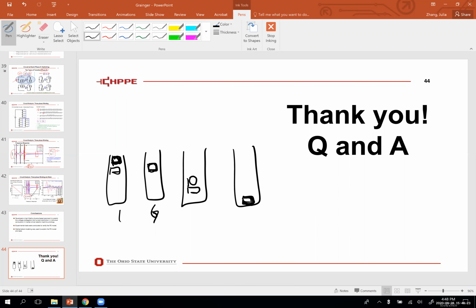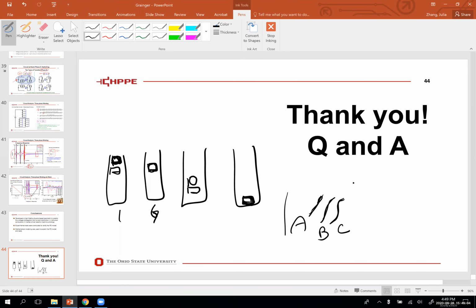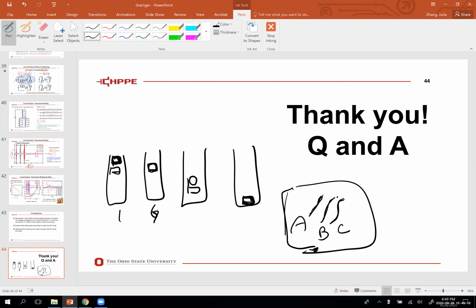So I understand what you're asking. One thing is how we use the results of this work. One way is to look at different winding structures. For example, typically the three-phase leads coming out are close together, but we also try to distribute the three-phase leads, not just put them together. Maybe the phase A lead comes out from this pole, the phase B lead from the next pole, then phase C from, for example, the third or fourth pole. In this case, we use the model to run it directly and look at the voltage stress between two phases. We can easily predict the voltage between two phases. Does that give us a lower voltage compared to the baseline model, or an even higher voltage stress between two phases?